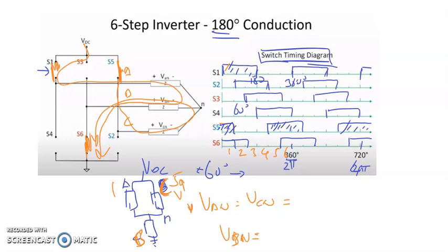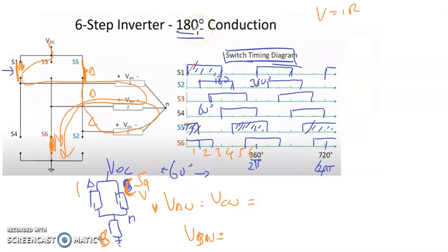Okay, we shall calculate these two based on Ohm's law, V equals IR. First we find the total equivalent resistance across the load, composed of loads A, B, C, which we assume each has a resistance of R. So R equivalent is the parallel branch of A and C, plus branch B.